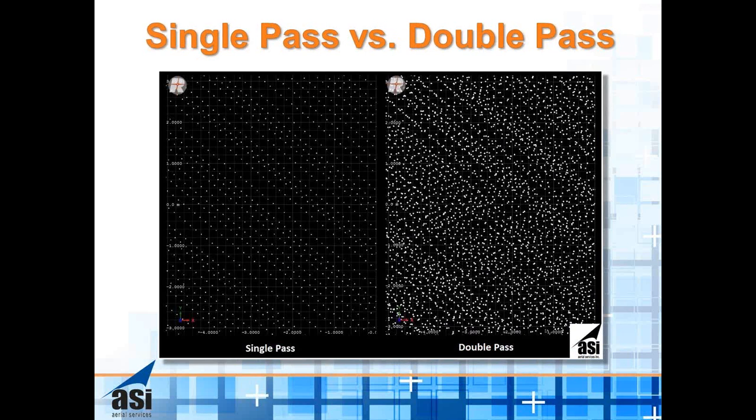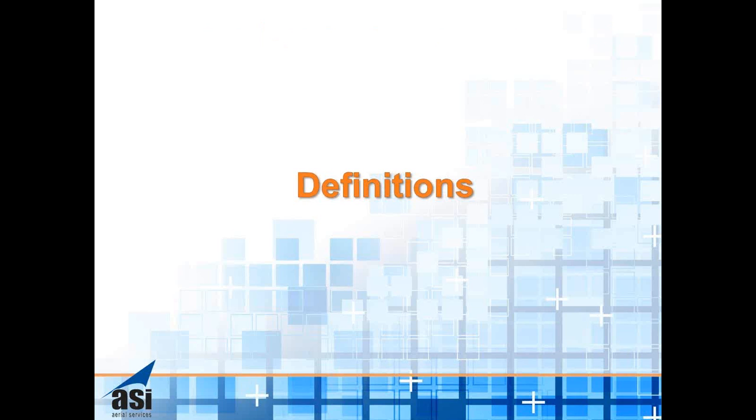When you look at data collected, some people want to know what the difference is in a single pass or a double pass. You just collect a lot more points. In a transportation project, a mobile scanner is going to do 600 to 1,200 points. I'm not going to be able to collect that many points, but if I flew a double pass on an area for specific issues, I could collect up to 80 points in a 500 to 1,000 foot swath.